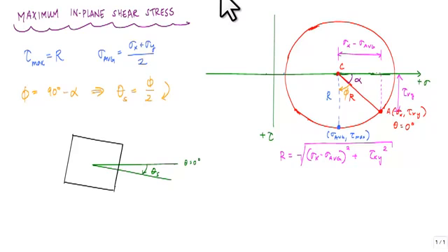And now at this location on this theta s, I have a positive shear stress, which would be on the plus face going in the plus or positive y direction here. I'll draw the rest of the shear stresses out. And the normal stress associated with this point is sigma average on all sides, because even if I look at this side over here, this point also has sigma average, and that means that I would have a normal stress on all sides.